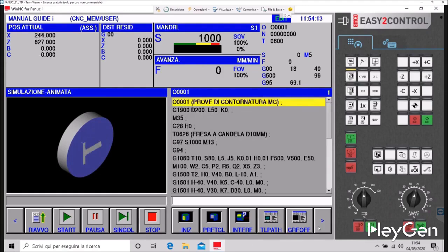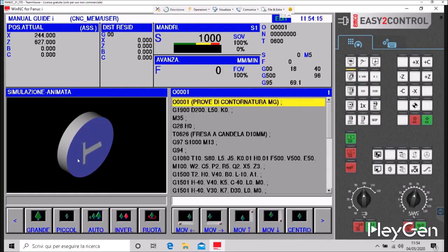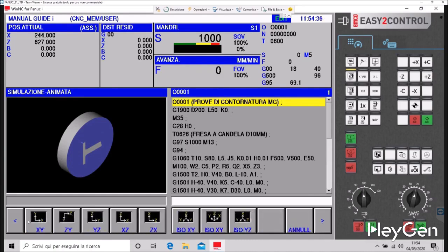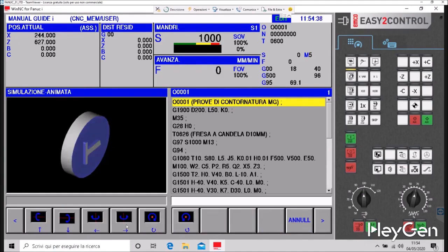And regarding the entry, if we need to create a shape like this, we can set it tangentially, directly, or as an arc. If we need to create a recessed shape like the one we saw, initially we have to be careful, otherwise it will leave us with an entry bevel, which is that ugly thing we saw before. We put the wheel, we turn it, and there you have your T.